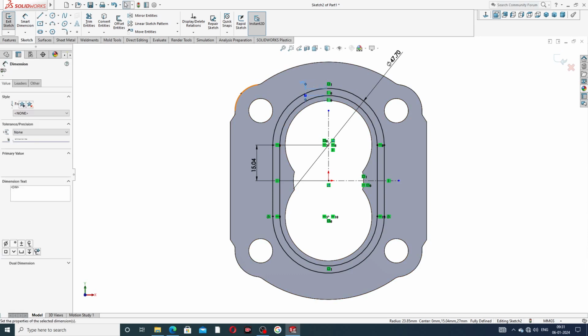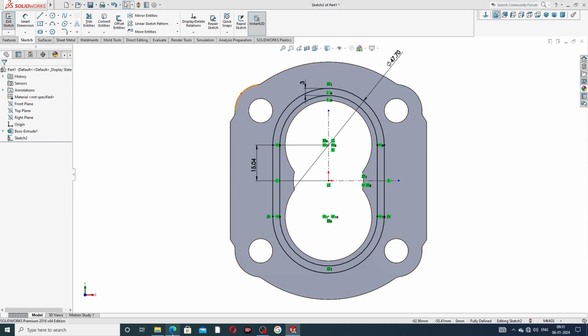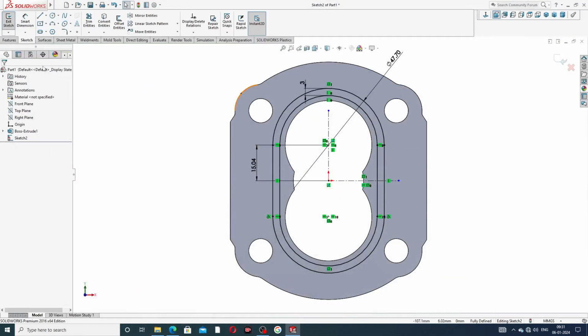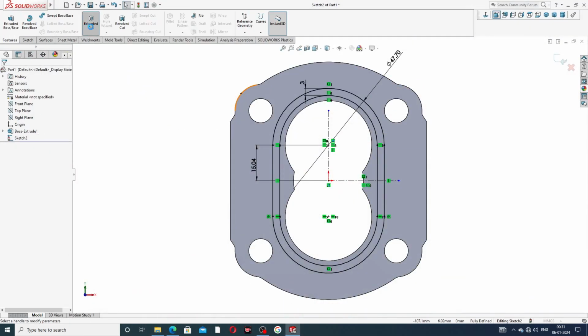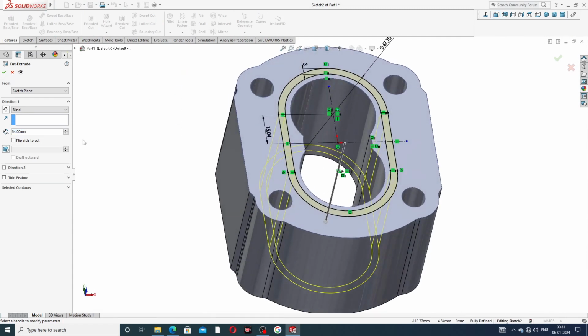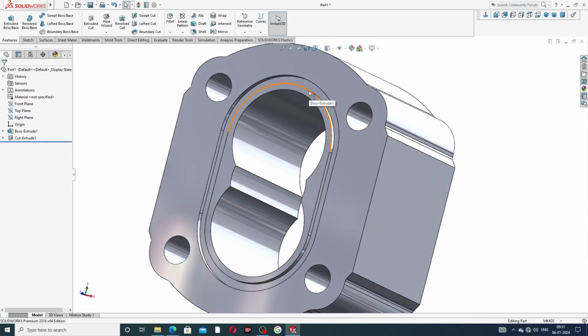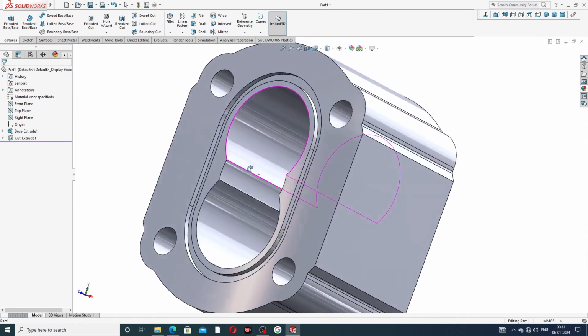And this offset is used here, and the cutout depth of only 2 millimeter is not mentioned here, but this is a 2 millimeter cut, and use Extrude Cut. Extrude cut is only 2 millimeter because this uses a rubber belt. 2 millimeter is perfect, and click OK. And a rubber washer is used here, and this is very nice looking.